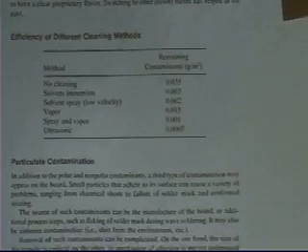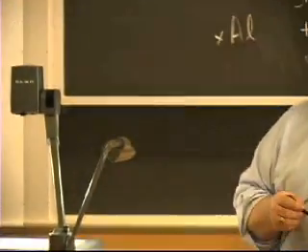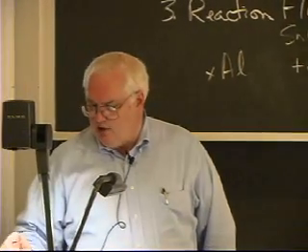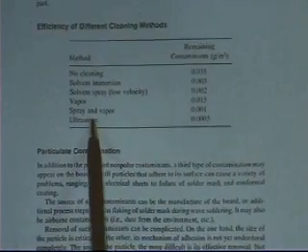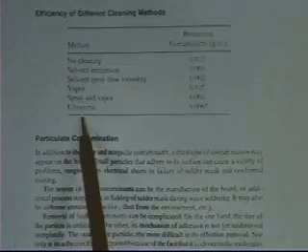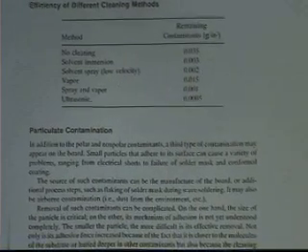And when you pull it out, you're pulling it out through this film of grease. By spraying it on, you basically get rid of that problem. You just wash it off. You get a little bit lower. And so vapor degreasing is the best, spraying and then vapor degreasing. Spray and vapor, you're down to 3% of what you had originally. And ultrasonic will get you down even lower.